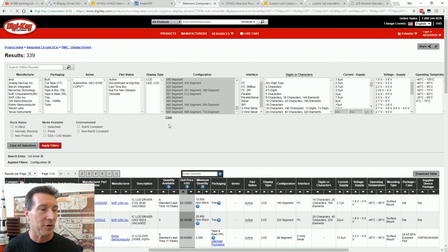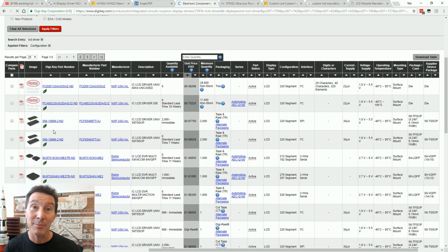So we can apply the filter and have a look at the chips available, and they're going to be reasonably large pin count LCD drivers. Here's one from NXP, for example, the PCF8545. That's an old Philips thing. I think it's an old Philips part number, 80, and I've sorted by price here, so lowest one first. So it looks like the lowest one that might do the job, 80 by 4. No, that's not going to do it. 80 by 8, 87 cents, $1.40. Getting a bit pricey.